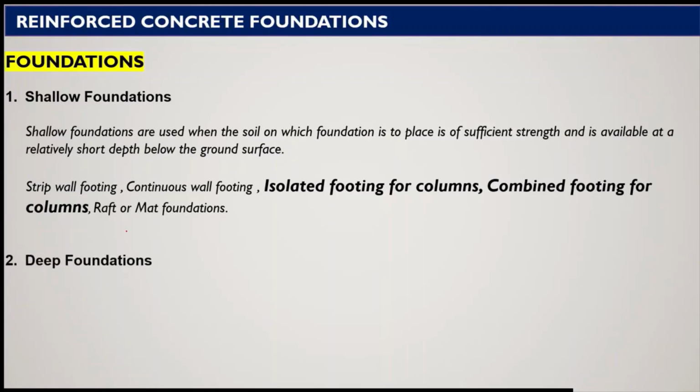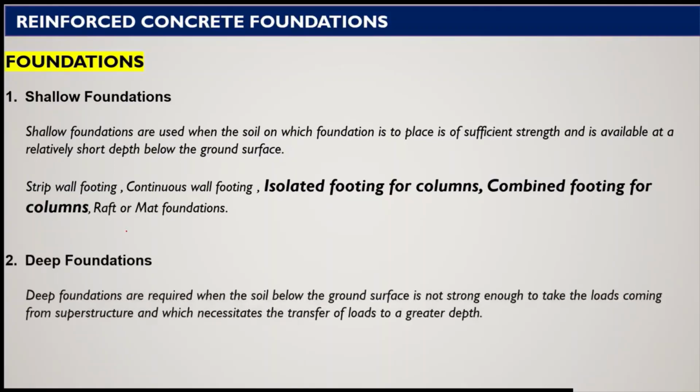Now, deep foundation. Deep foundations are required, in comparison to shallow foundation, when the soil below the ground surface is not strong enough to take the loads coming from the superstructure, and this necessitates the transfer of load to a greater depth.